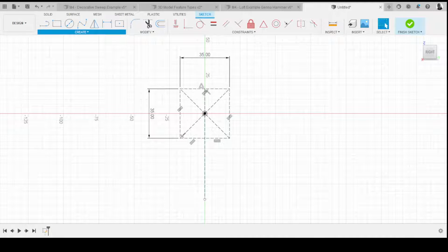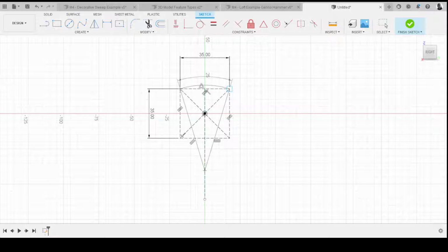And then finally, I'm going to create that center point arc by clicking the center point somewhere on this construction line we just created. The first end of that arc over there, and then draw it round. So we're trying to achieve something like that. That makes sense? So you just grab the center point. It's just like drawing a circle, you're just drawing part of a circle.